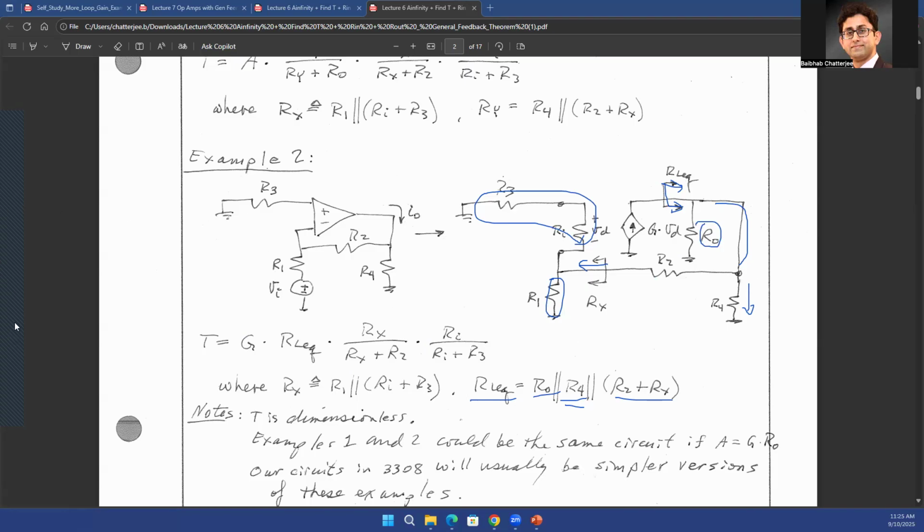All right. So I'll post a homework 2 today, which will contain problems where you need to find out the loop gain, basically the beta, and multiply it with the original gain A to get the overall loop gain A times beta. Questions? So the first answer, G times R, right. Why don't we account for R0?